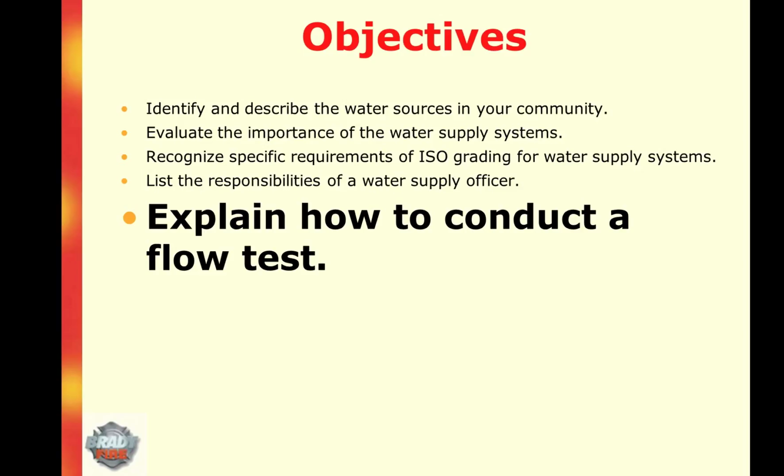Preparation is key to proper testing. You should always notify the utility and the community. Avoid peak demand times so that the public is not inconvenienced with brown water or low pressures. You should review utility maps to determine surrounding water main sizes.